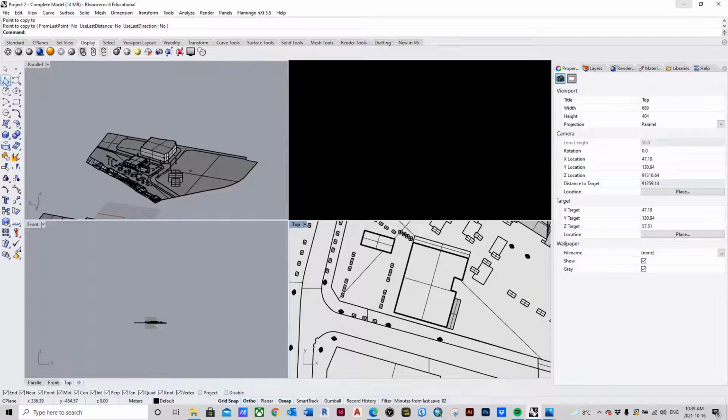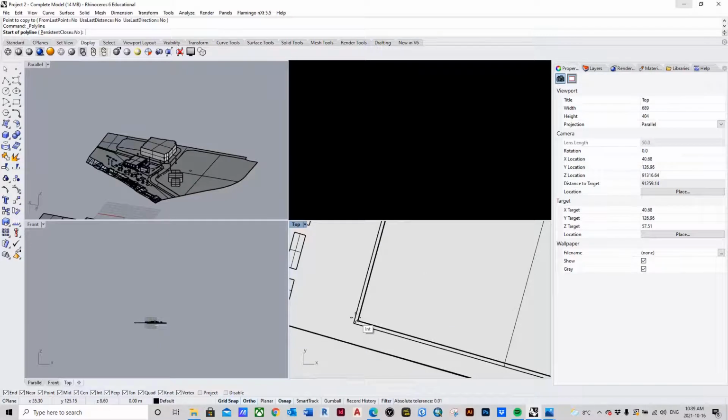All we're going to do is this, and again, this is just my method of doing the rotation: I'm going to select the polyline tool. We're going to shift down. This seems like a good point, because this is essentially the face that we want to be at 45-degree angles. We're going to select.